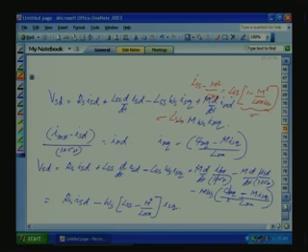So this equation we can effectively write as minus omega S sigma LSS ISQ. So this we will put as the feed forward term in the controller here, in the ISD term.